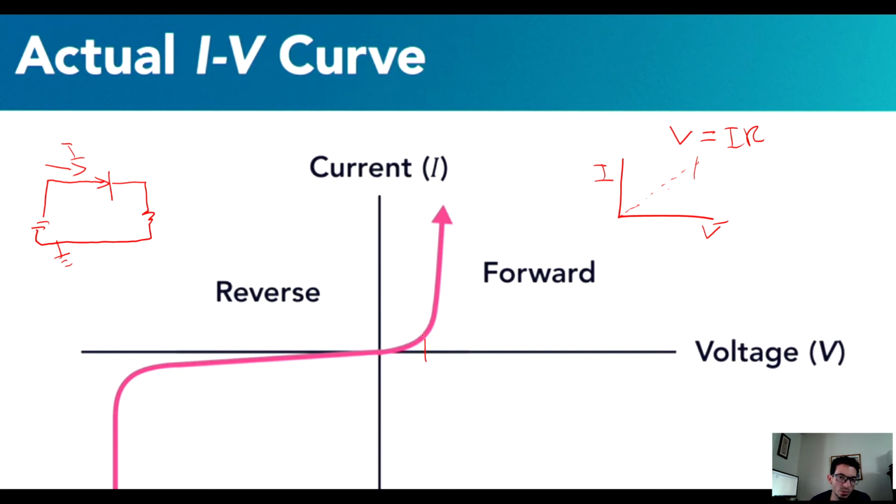At this voltage, you will have current that will increase exponentially. But if you try to reverse the direction of the current, this will not happen. It will act like an open circuit, and there will not be flow of current through the circuit, but there will be a little bit of reverse current through the diode, and this will happen in a voltage plot at this operational value, and then you have the breakdown current where the element breaks.